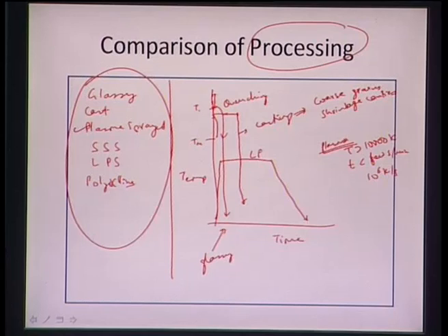So this is liquid phase sintering, and in liquid phase sintering, what is happening is we are allowing one phase to become solid, one phase to become liquid, and because of capillarity, that liquid tends to draw all the grains together, and that basically is consolidating the material.